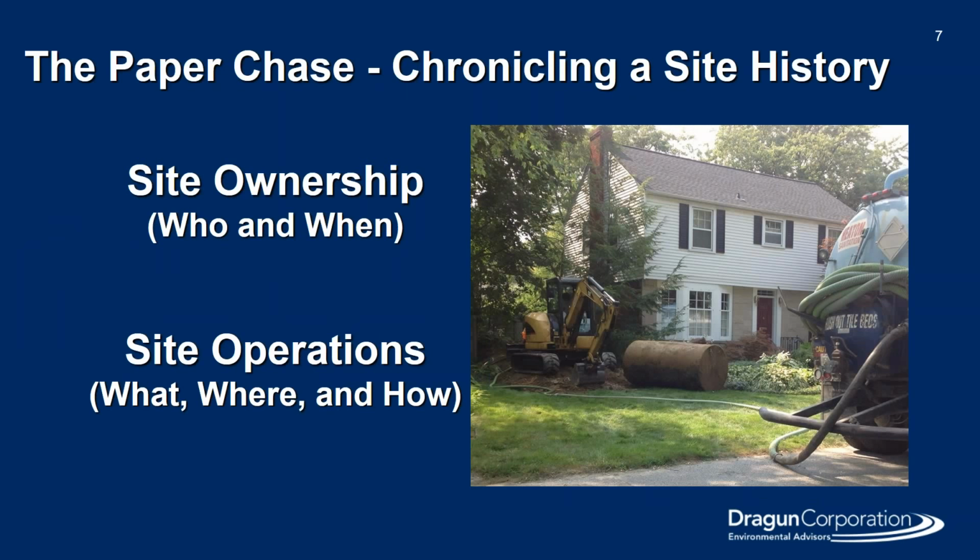Establishing answers to these basic questions as part of your CSM will be beneficial whether you are negotiating with a regulator, whether you're in litigation, or whether you're designing a remedial system. It may be that your research shows that you or your client is not even responsible for the release, or maybe only partly responsible. It may show that there are other chemicals that you should be looking for when you're defining nature and extent of contamination.